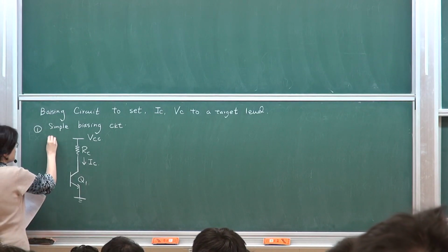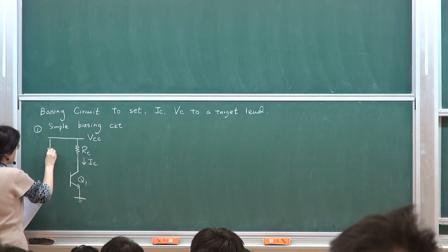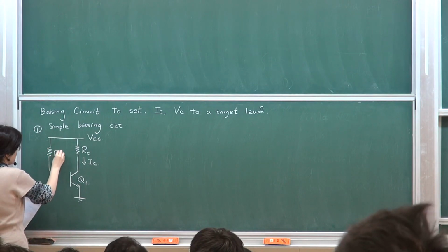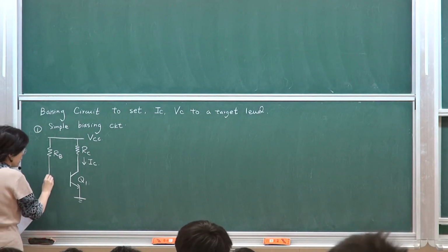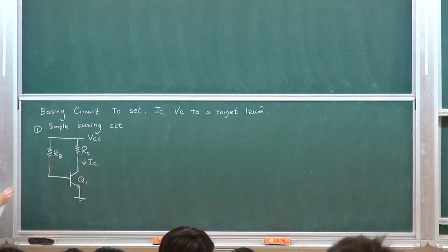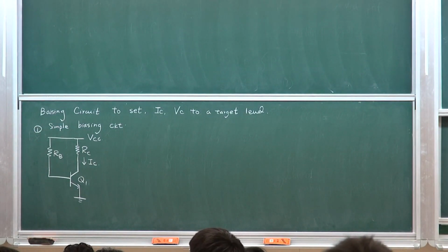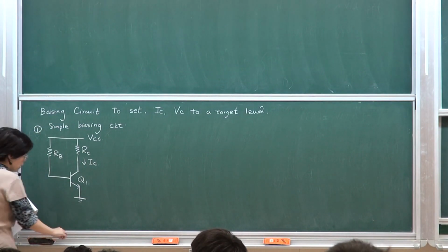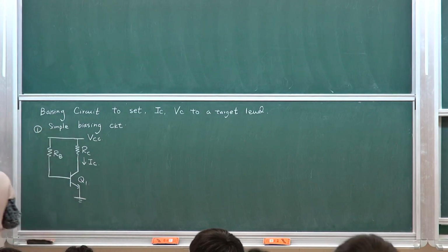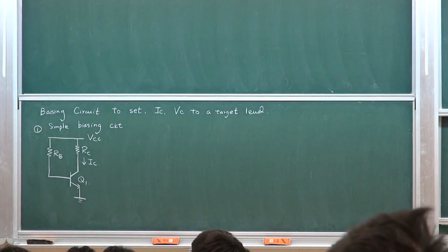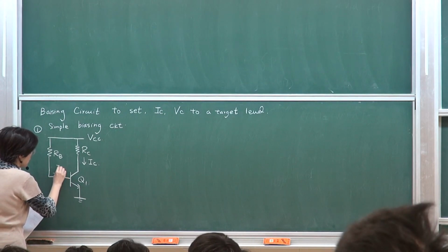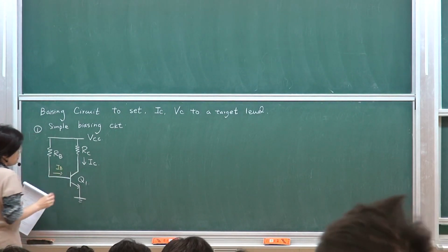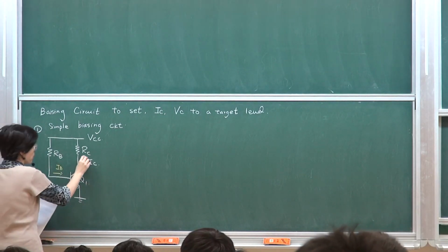So the way to do this is that I'm setting up base current instead. What is being done is I need to supply a base current and I use a resistor to establish this current. So if this is my setting, then think about what is being determined. If you look at this pathway, this is IC. This is IC I want to determine.